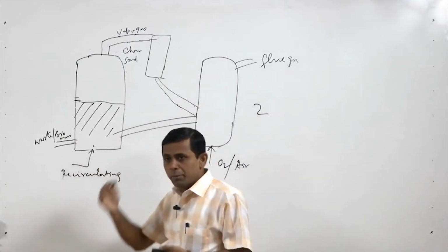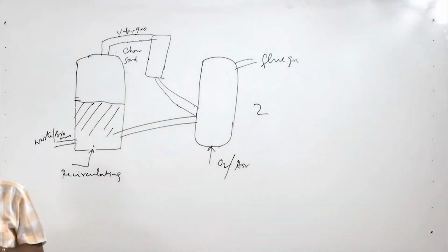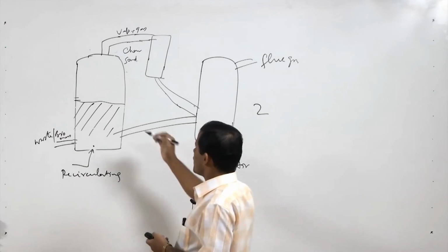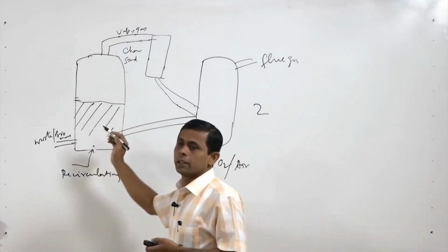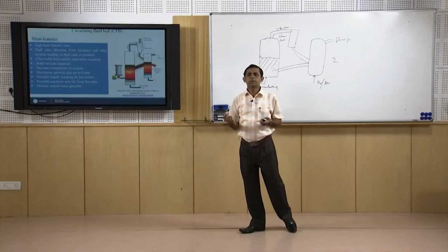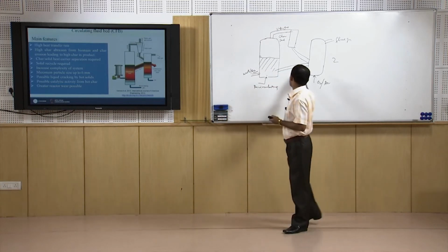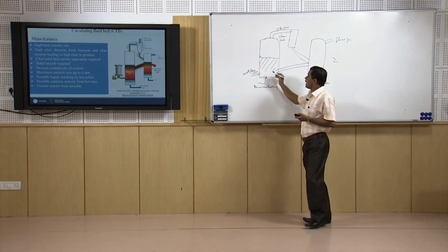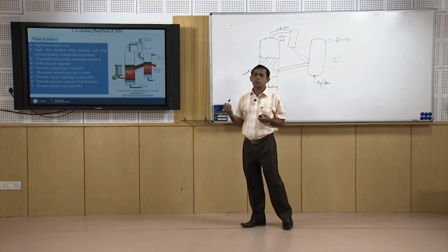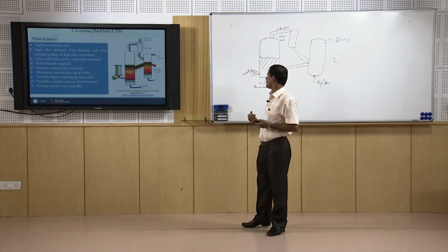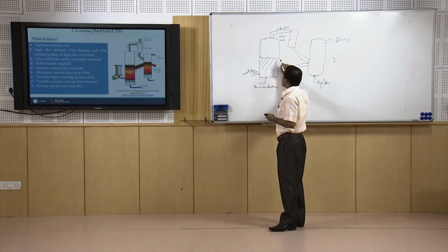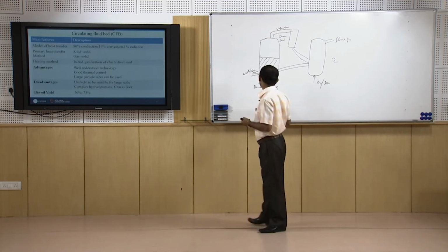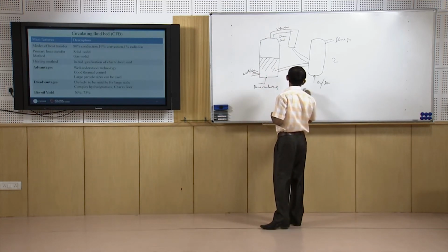So, this is the development of the fluidized bed reactor. Some part is recycled, the solid is recycled. Heat transfer is taking place here through conduction, convection and radiation, and the char or sand which is returned can also act as a catalyst, having some catalytic activity. Due to this, the bio-oil production is also very high, 70 to 75% bio-oil,